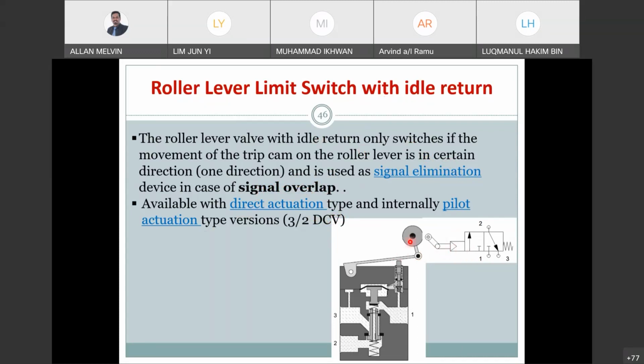So you can see here. If a cylinder is moving from the opposite direction, will this turn on or not? Let's say you have a cylinder here. The cylinder extends. If it extends, will this press down or not? If your cylinder is extending from this side, no. It extends, this goes to the back, but it will not press this button. But if you have a cylinder here moving forward, this cannot move, it will press this one.